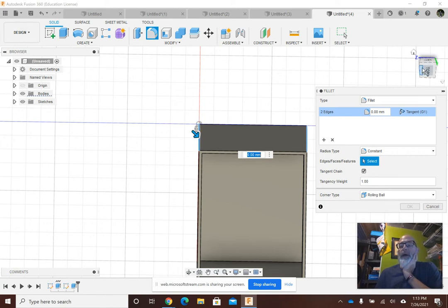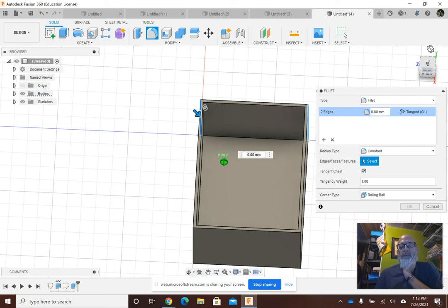2. I'm going to change my angle by clicking on the view cube and rotating it up. I have 2 edges selected. Notice my palette. It's telling me I have 2 edges selected. I want this outer edge here, 3. And this outer edge, 4. Okay, I have a dialog. If you look right down here, yours could be in a different position.